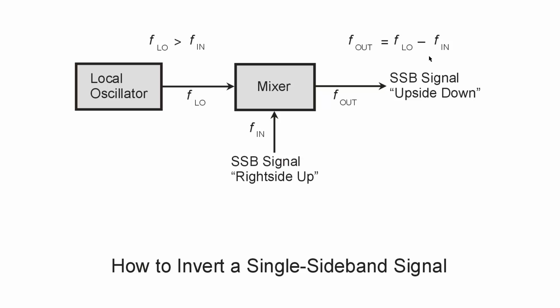As an example, suppose that the carrier wave of the single sideband signal is 3 megahertz. So this is a 3 megahertz signal, suppressed carrier frequency of 3 megahertz, upper sideband signal. Suppose the local oscillator is 5 megahertz, just a plain carrier. Then the output is the difference. We choose the difference output, not the sum, which would be 2 megahertz suppressed carrier frequency.